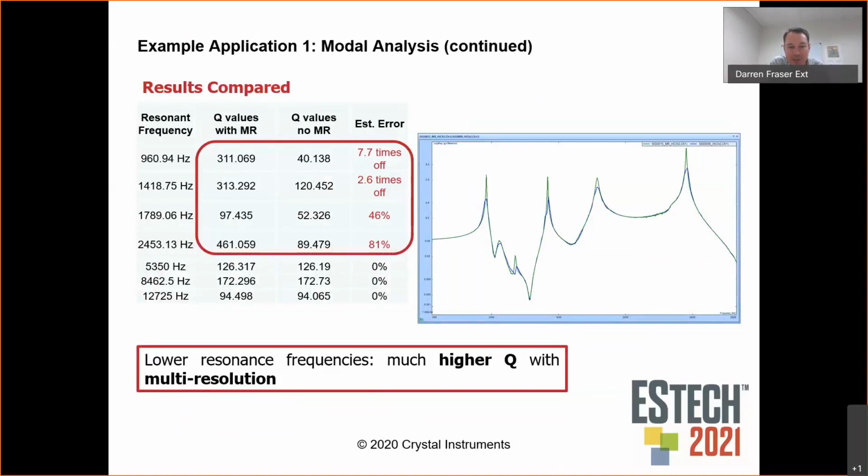And with that, you can see a larger difference between the multi-resolution spectrum and the original FFT spectrum. Again, that difference stems entirely from the fact that the multi-resolution spectrum is able to give us a delta F of about 1.5 hertz, where the original spectrum can only do at best 12 hertz.